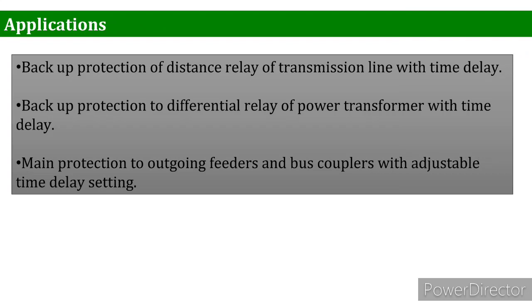Let me mention some applications of the definite time overcurrent relay. It is used in backup protection of distance relays of transmission lines with time delay, backup protection of the differential relay of the power transformer with time delay, and the main protection to outgoing feeders and bus couplers with adjustable time delay settings. Some of these relays you are not familiar with now, but in the upcoming lectures we will be discussing distance relays and differential relays also.